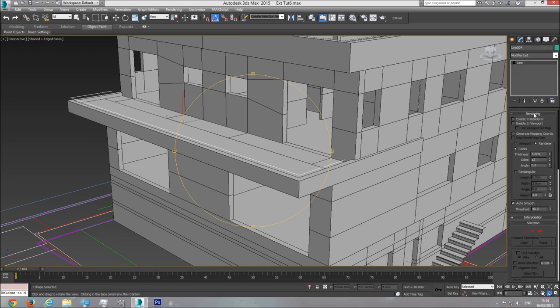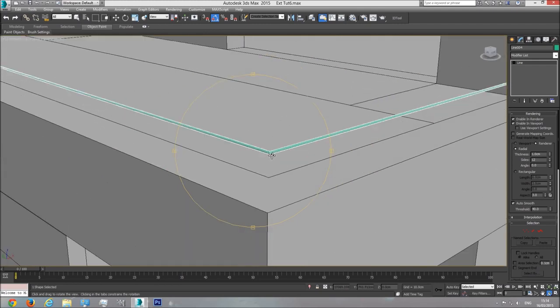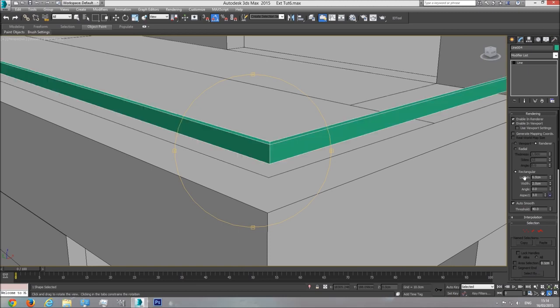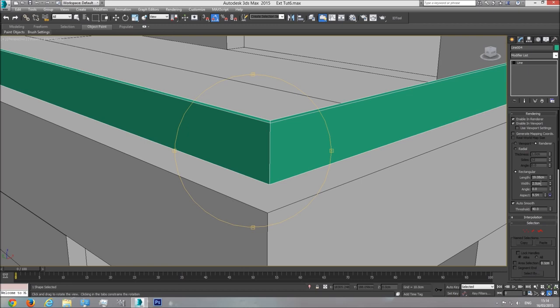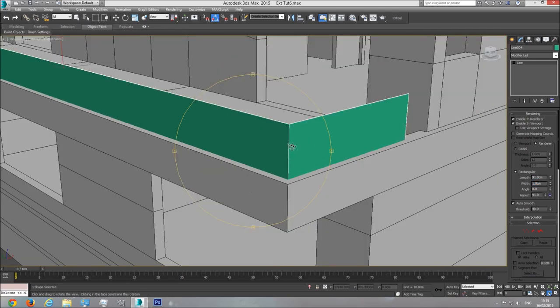The way I'm going to do this, I'm going to go to the rendering setup in the modify panel for this line. I'm going to enable these two, enable in viewport and enable in rendering. Now it's transformed the line into a cylinder form, which is because we're on radial. When I click on rectangular, it gives a height of 6 centimeters, or how much you want, and a thickness here of 2 centimeters. So the glass is going to be something like 1 centimeter thick, and the height is 91 centimeters.